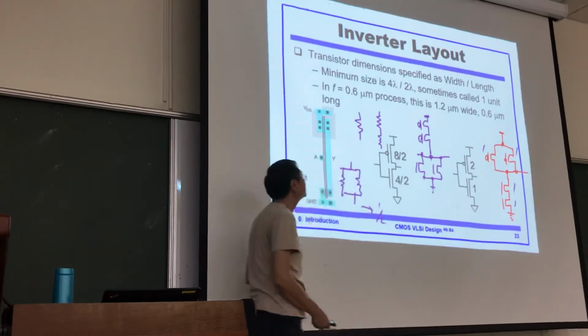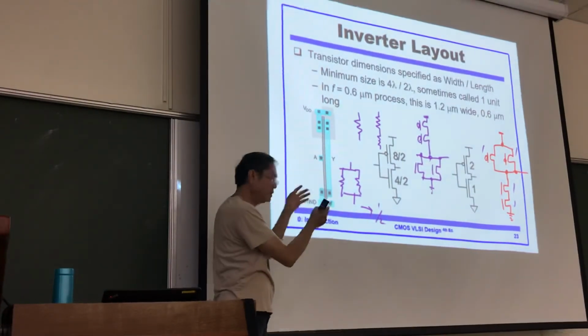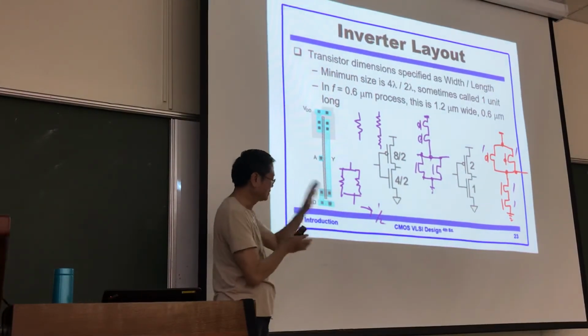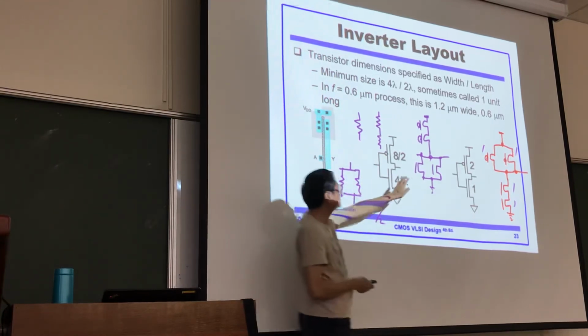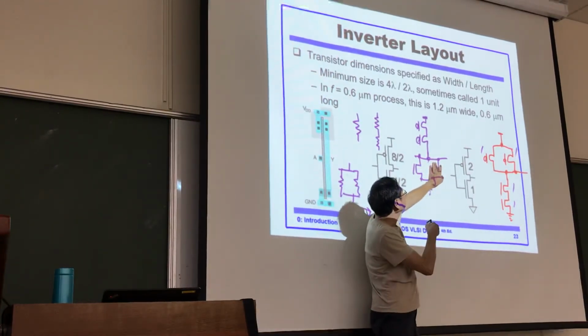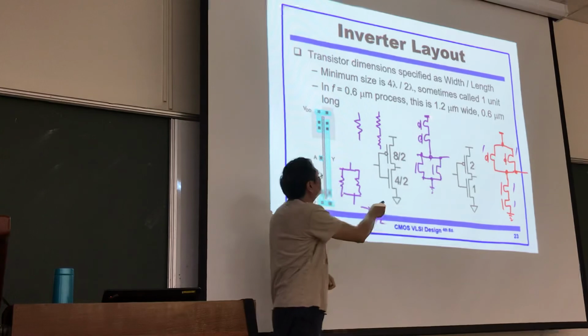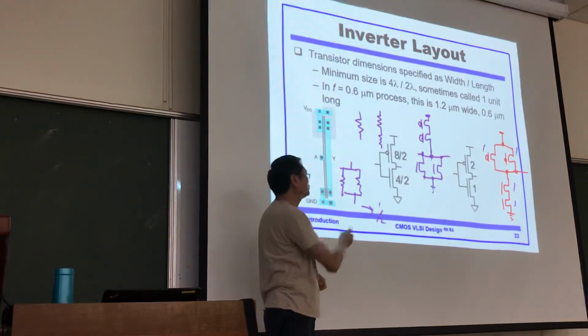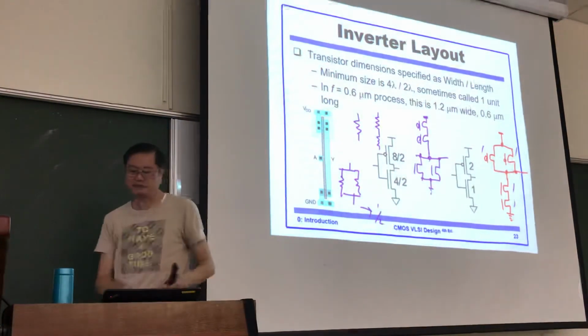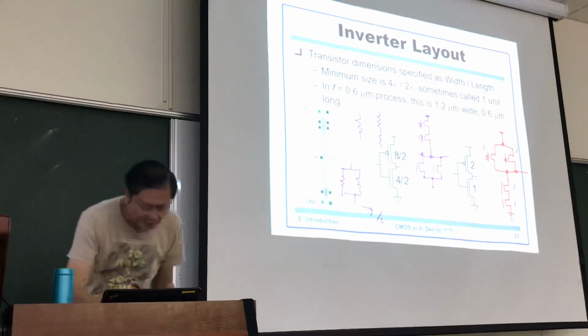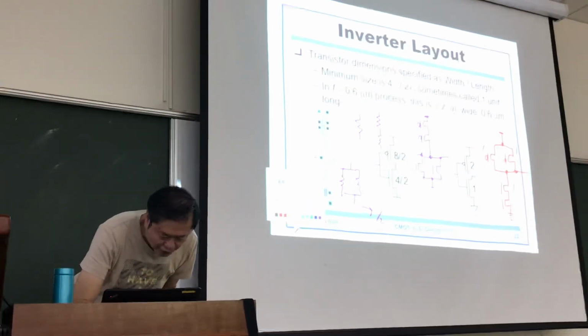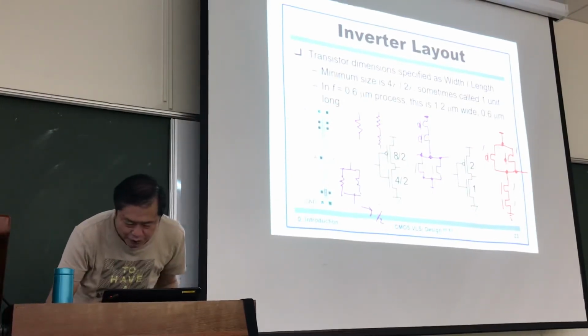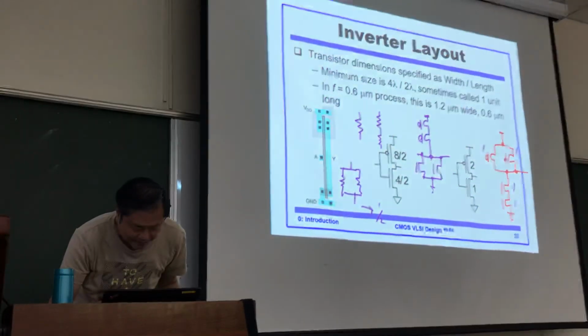Although both are on, it's going to be faster, but we consider the worst case. So only consider one NMOS, and you're comparing two PMOS in series and one NMOS transistor. So what is the size? For switching speed, 0 to 1 and 1 to 0 are the same.